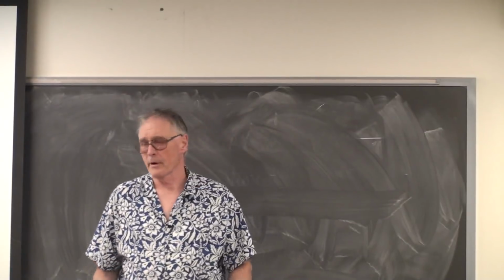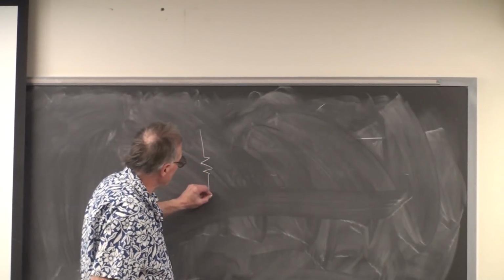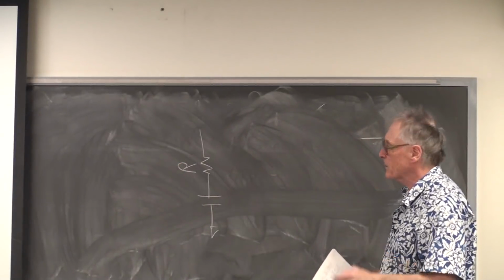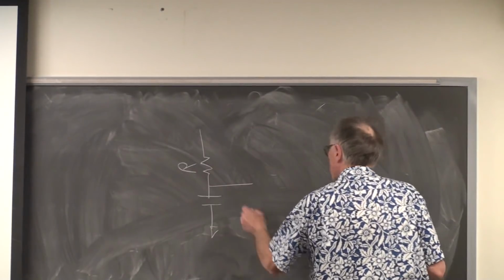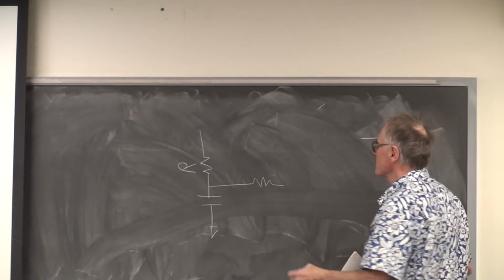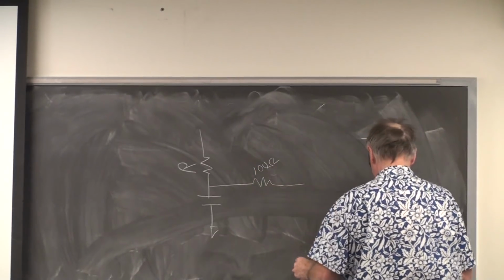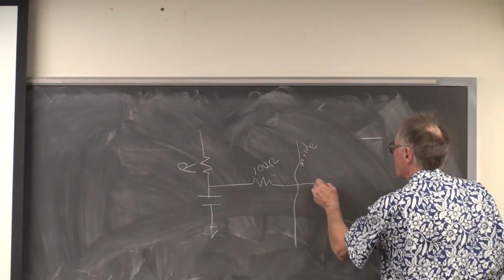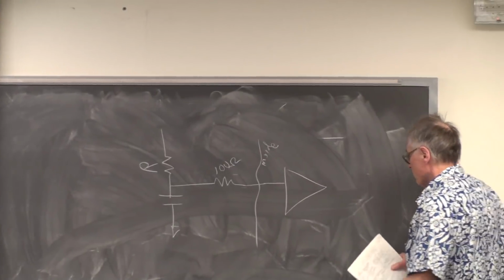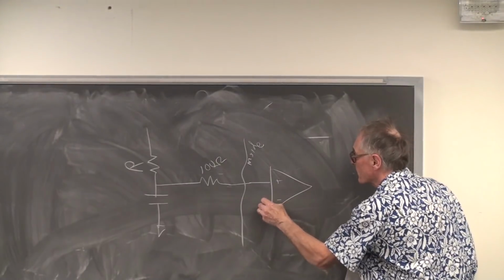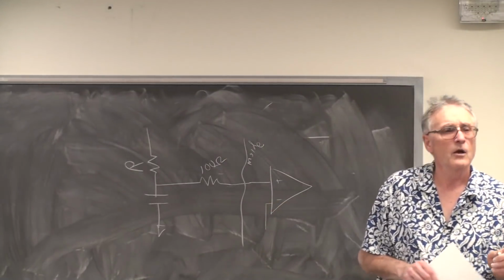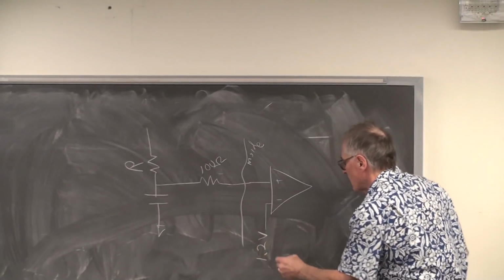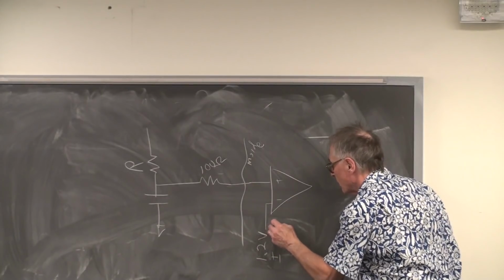So what we're going to do is write a program that uses this circuit to measure a capacitance. You're going to know the resistance. You're going to put this through a 100 ohm or 300 ohm resistor or so. You're going to run this into the CPU. Now, this is outside the CPU. This is inside, where there is the comparator. This is the positive input. The negative input of the comparator is going to go to yet another peripheral I haven't mentioned, which is an internal precision voltage source that produces 1.2 volts plus or minus 0.06 volt.